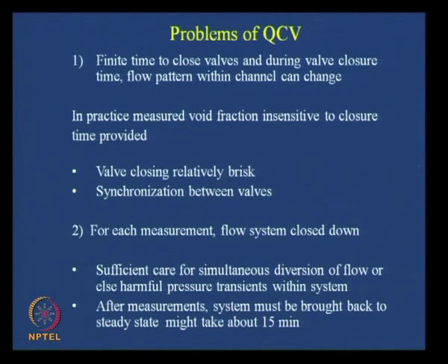Again you have to start after every reading of hold up. So, therefore, what you have to do? Every time first you have to stop the flow, and maybe you have to divert it to some other area, or you have to stop it completely. Then once the measurement is done, again you have to start the flow in this particular direction. Again you have to wait for the entire system to attain steady state, and again you have to take measurement. So, therefore, it is a very time taking process, and in industries you very well know that we cannot start and stop the flow in this manner so very frequently.